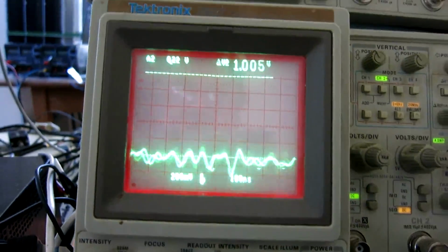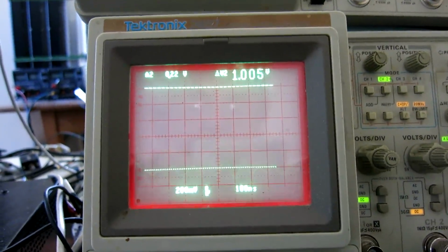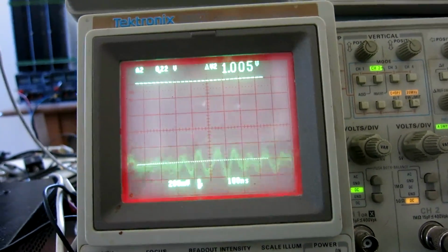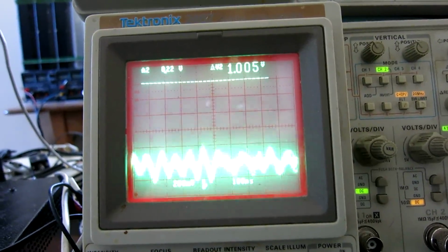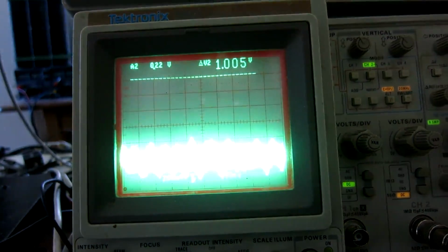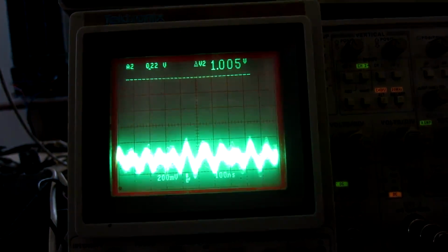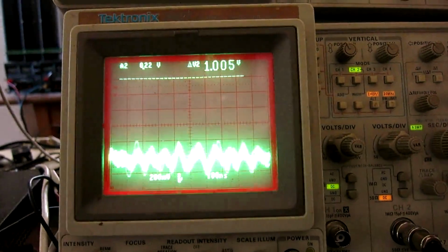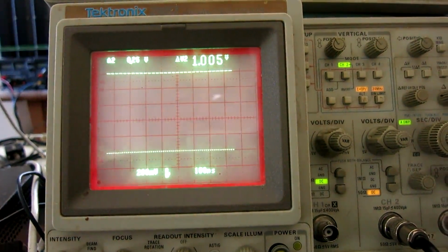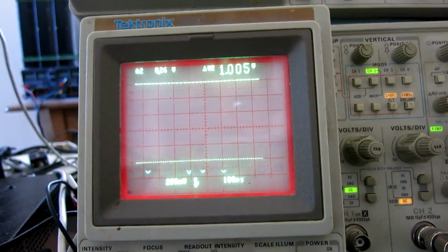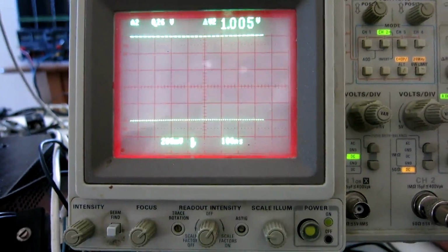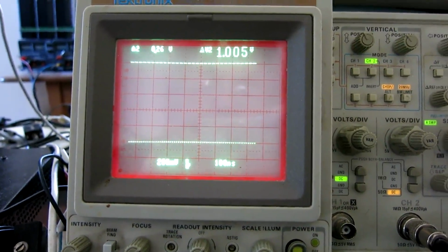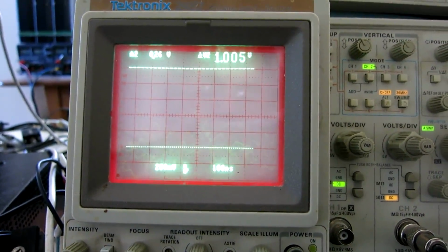This is what the signal looks like on an oscilloscope. There are peaks up to about 1 volt. There was one a little bit above. But most of the time the signal level is 200 millivolts or so. And you can see here, when triggering, not quite as often. So this is the signal that the receivers can take.